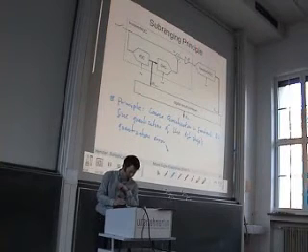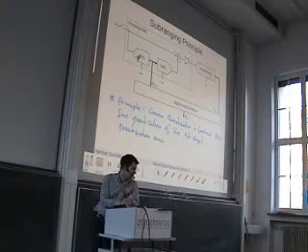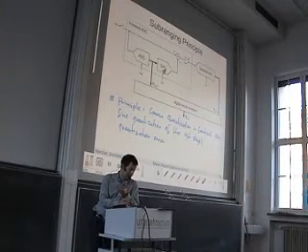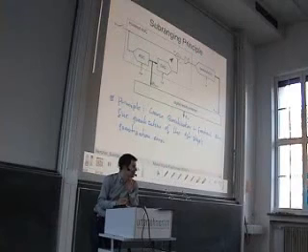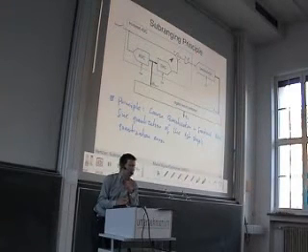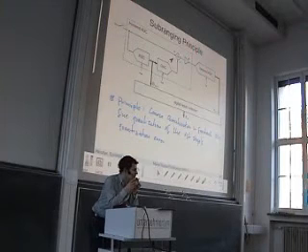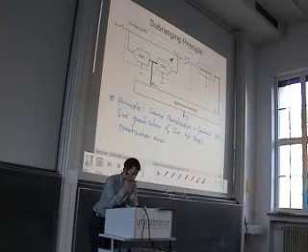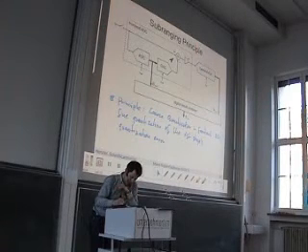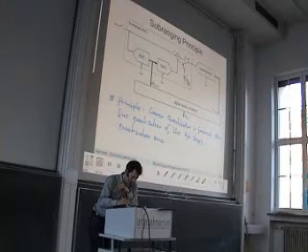If you look at this structure, then we can see here we make an ADC conversion, a coarse one. We convert the result back with a DAC, and we subtract it from the sampled value. This is a picture that you saw, I guess, in the first or second lecture of this course, where we tried to extract the quantization error. This is exactly the case here. This here is the quantization error.